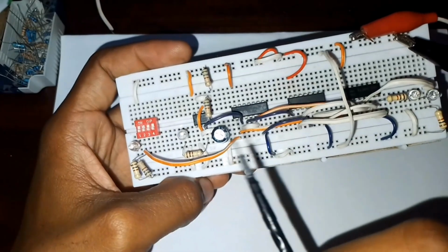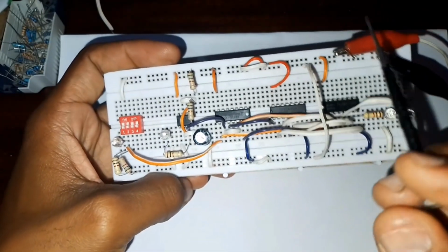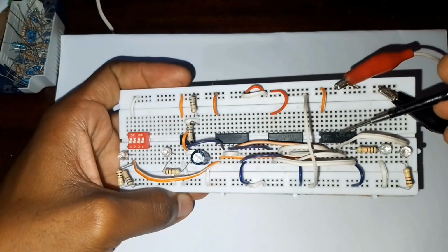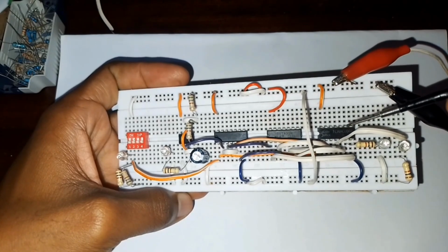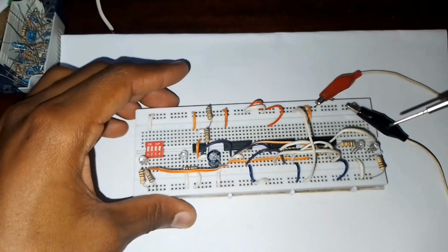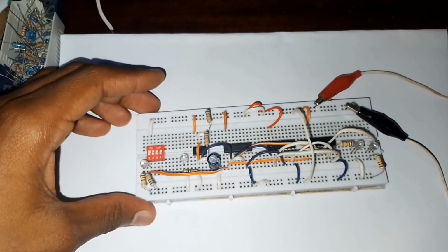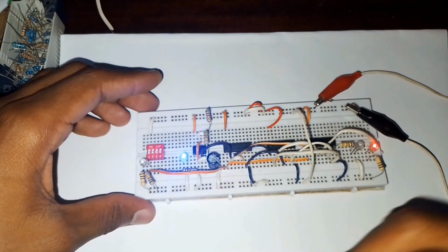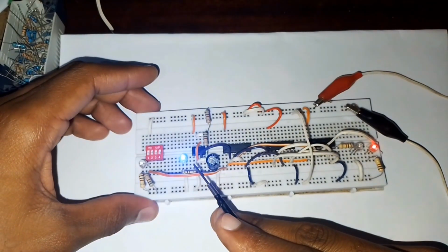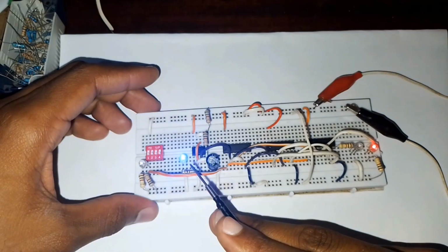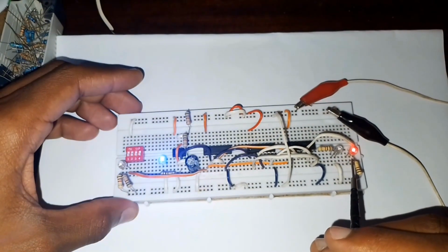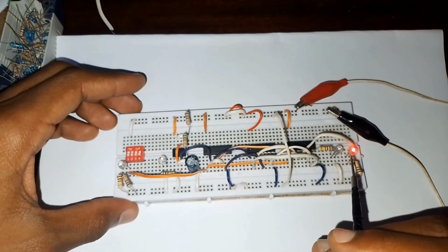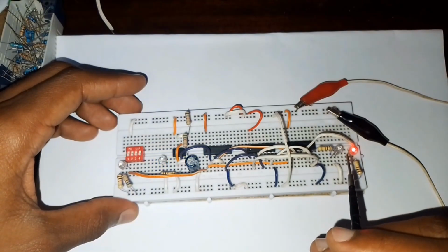So I'm going to turn on the circuit. I'm using a 5-volt power supply. You can use any from 3, but please check the ratings of your integrated circuits. Make sure that you don't damage them. So I'm going to turn on, and the circuit is on, and immediately you can see this clock signal is on, and in our output section the red LED is on, showing us the circuit is at normal state when there is no data.